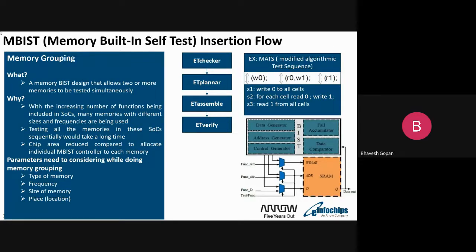and to test all those memories, we must have MBIST. Testing all the memories sequentially would take a long time, but that is another point, and I will come to it later. Also, chip area is reduced compared to allocating individual MBIST controllers. This is now more advanced.